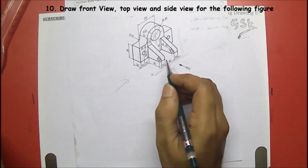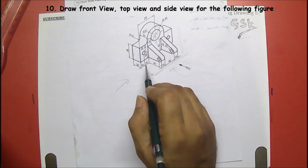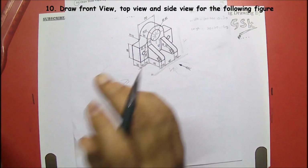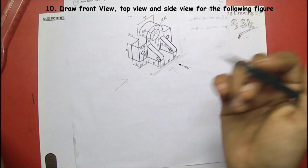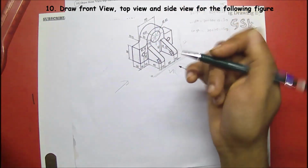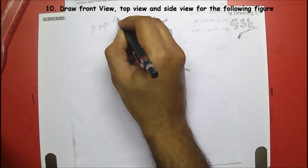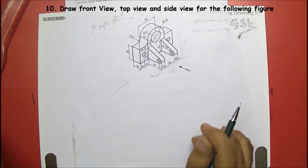If you are going for third angle of projection, the left side of the figure would be falling on left side, the right side of the figure would be falling on right side, and the front view would be coming down and top view would be going up. So I'm following the first angle of projection for this type of problem.